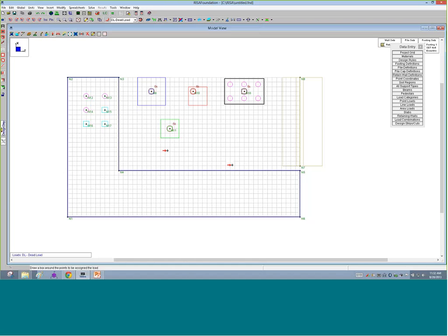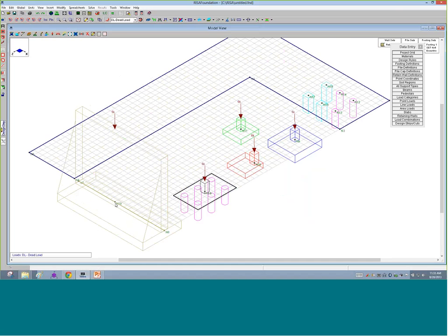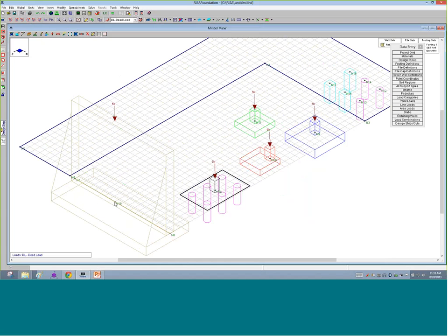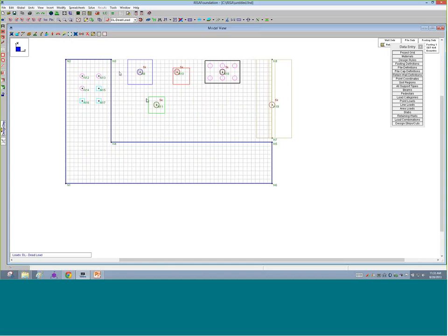And I'm going to put that on my pile cap. And now I can also put that right on my retaining wall. Retaining walls can get line loads or point loads. It's up to you here. You can draw them in, and let's take a look. When you draw that point load at that location, a node shows up at the bottom, but graphically it shows up at the top of that wall. So actually we're pulling that 5 kips through the entire stem wall. Okay, if we look back at that in plan view, we see that there.